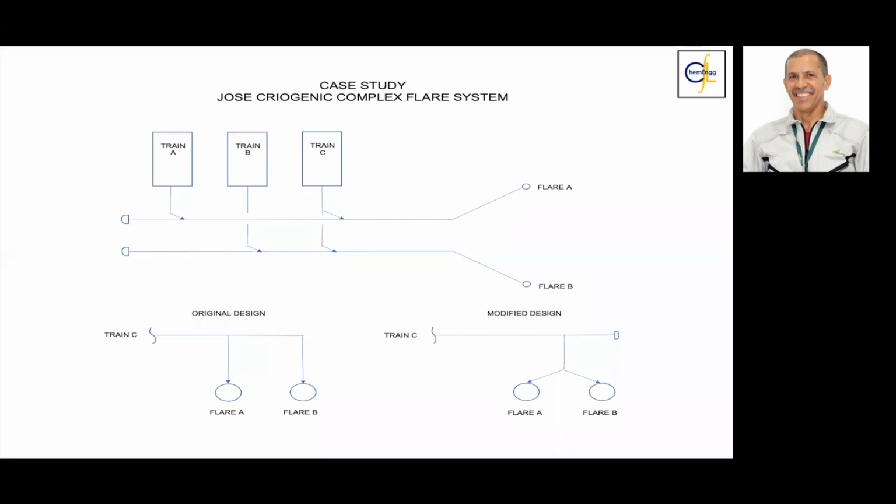go into the 3D model, if we participate in the 3D model review, it is very important for us as a process engineer to participate in those model reviews. Even if you are told not to participate, please talk to your project manager to be there. Because most of the time, the piping group makes the best arrangement for them. And then if we see there, we have additional costs because you have additional material to be introduced in that arrangement rather than using that arrangement.